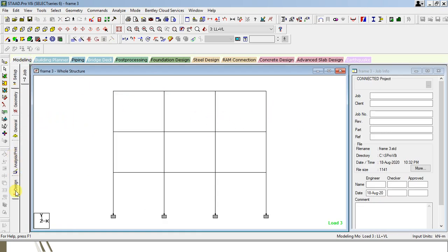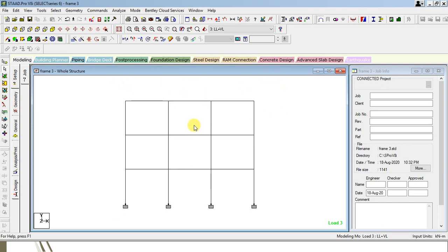Again if you want you can plot the reports also for different options. You can take out any 2-3 types of reports. In the first one the analysis because of lateral only, in the second one the analysis because of vertical loading only, or in the combination of lateral plus vertical. Whenever we are considering the earthquake load and wind load, without consideration also you can plot the different shear force and bending moment diagrams, and with consideration also we can plot the shear force and bending moment diagrams for this. Okay, similarly you can add n number of bays for this beam over here.